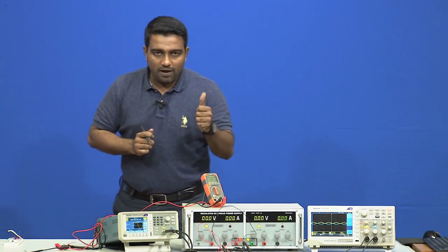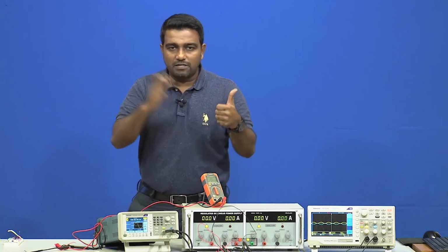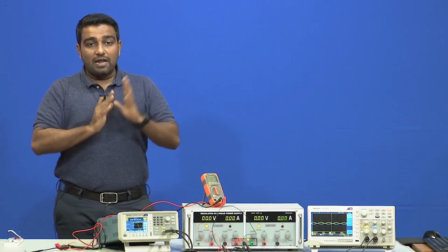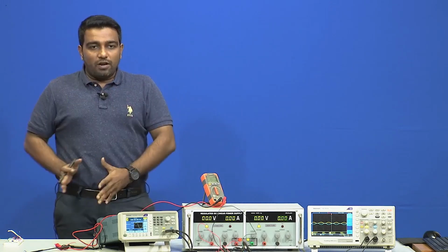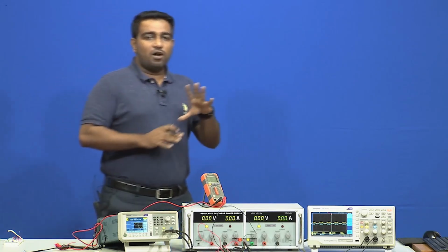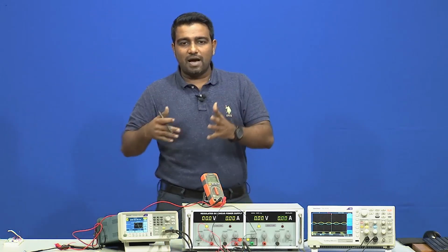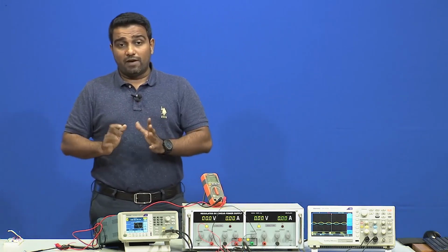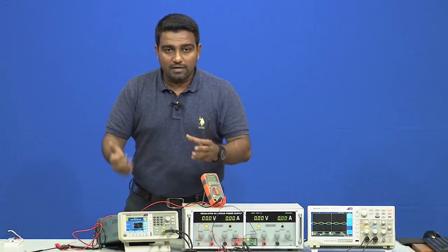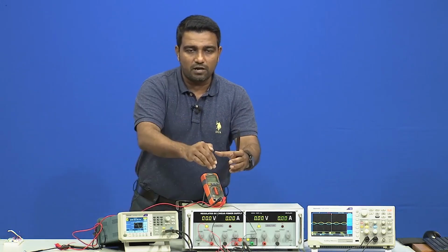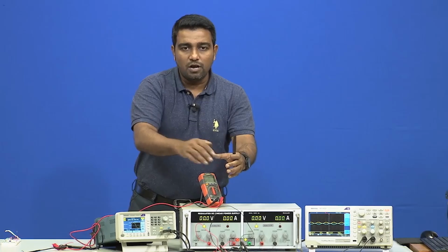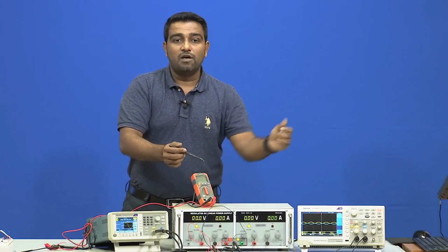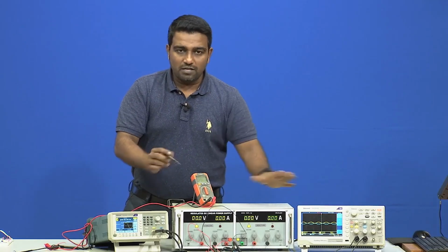We have seen an inverting amplifier. We applied the input at the inverting amplifier, we measured the output, and from that output, V out by V in, we measured the gain of the inverting amplifier. We measured the theoretical gain of the inverting amplifier, and we already know that V out equals minus RF by R in into V in, that is the formula for your inverting amplifier. Then we saw a breadboard, and we connected the frequency generator signal to the inverting input, so that the output is inverting, that is out of phase, a 180-degree phase shift, which we can see on the oscilloscope. This is what we have done.